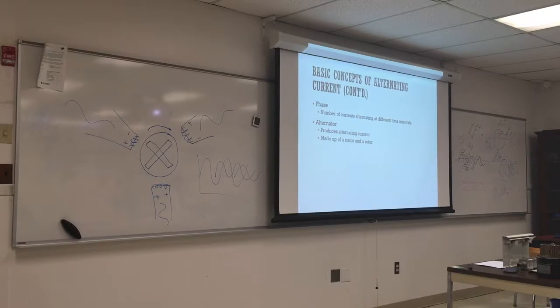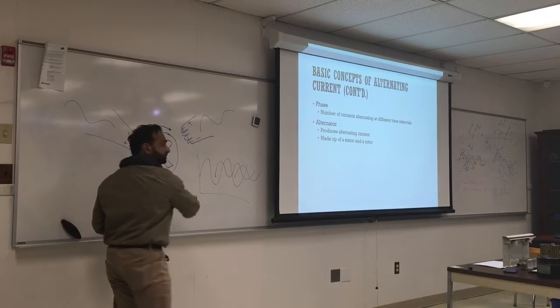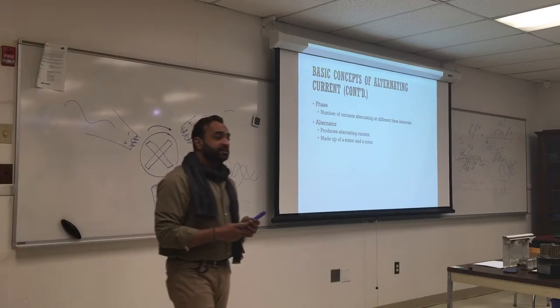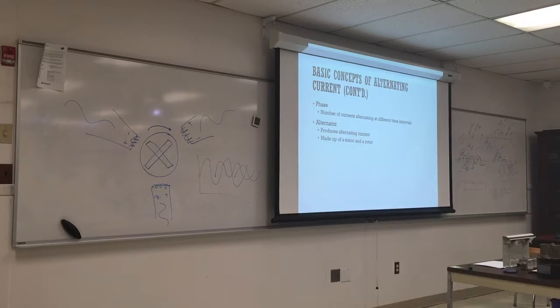There's no way that this rotor will stop because it's always off balance, rotating and pushing. It's not going to be in equilibrium because it is off-centered. With single phase, we have one current. There's a possibility that the motor would not start. For example, did you ever have a motor that you plug in and it starts humming, but it does not turn?